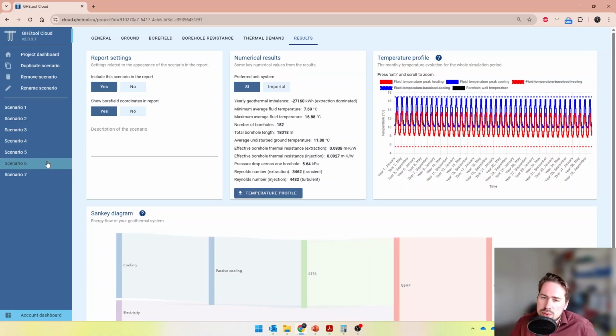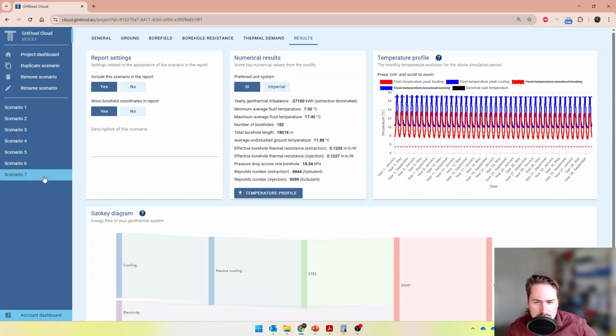And this is relative to the one with the double U-tube, since here we're also already in the rather turbulent region. So if we go from a double U-tube, which is in turbulent region, to a single U-tube, which is turbulent, our convective heat transfer is already really good, and we're just lowering the number of U-tubes. So that's not beneficial. Going from a double to a single U-tube can be beneficial, typically when your double U-tube is laminar and your single U-tube is turbulent. But if it's both turbulent, in this case, it's not beneficial.